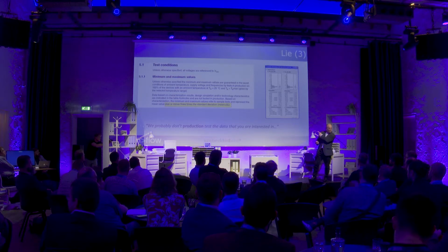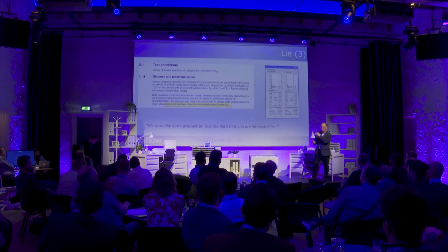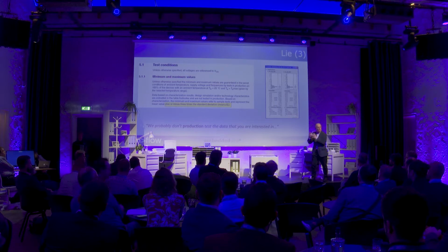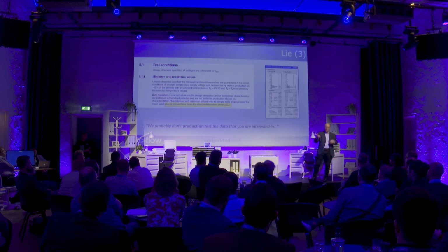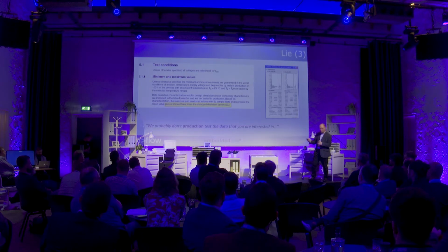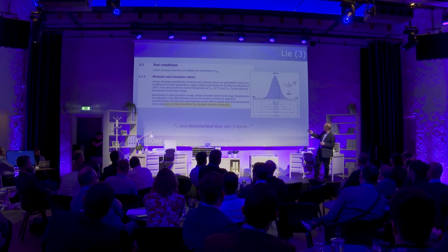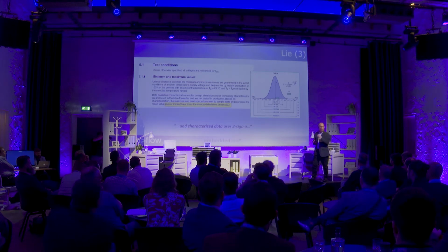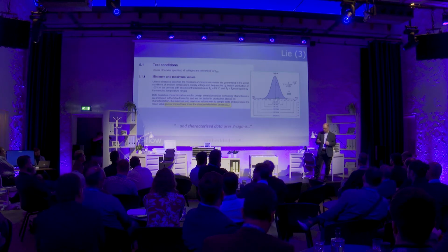And then here's the real kicker. From that first wafer, we measured our stop mode currents, and we worked out a kind of distribution of the values. And what we published in the data sheet is plus or minus 3 times the standard deviation. Just if you need a little refresher on that, here's our standard deviation curve, and 3 sigma is here. So not every unit that you actually buy will meet that characterized value.